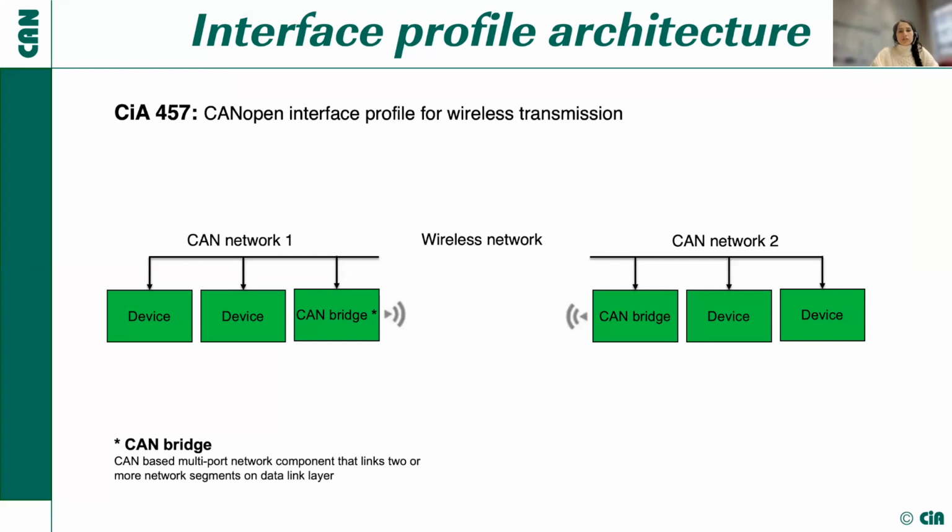Here, as I said, interface profiles specify the CANopen CC or CANopen FD mapping to other communication technologies. In general, for devices without application functionality, CANopen interface profiles are specified. The interface profiles are similar to the device profiles, but they don't specify process inputs and outputs. Instead, they describe the functionality of another application-independent network technology. For example, here